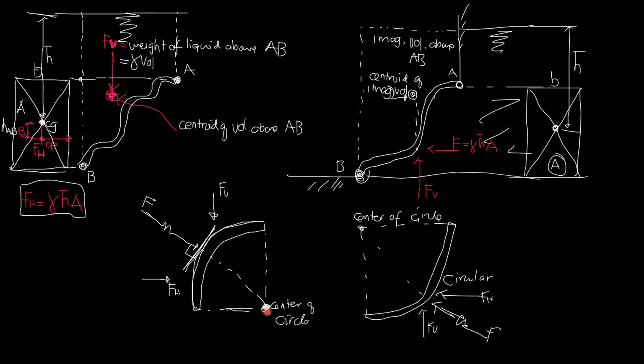Therefore, since the moment of the resultant is equal to the sum of the moments of its components by Varignon's theorem, then the moment of F about the center is 0. And that's also the sum of the moments of its components, Fh times moment arm minus Fv times moment arm, or Fv times moment arm minus Fh times moment arm, considering counterclockwise as positive.